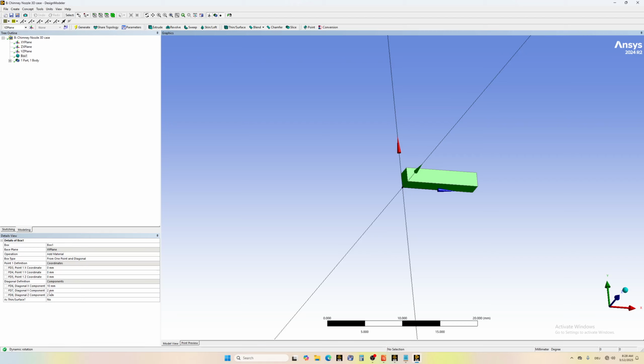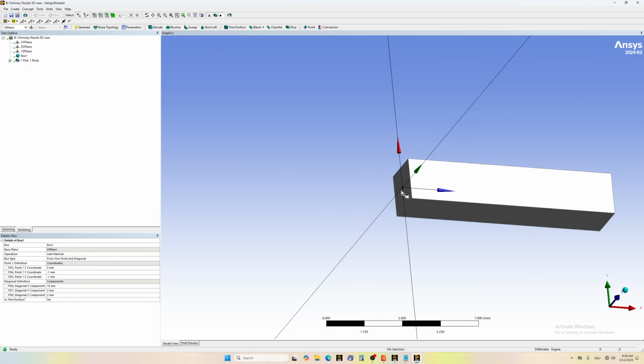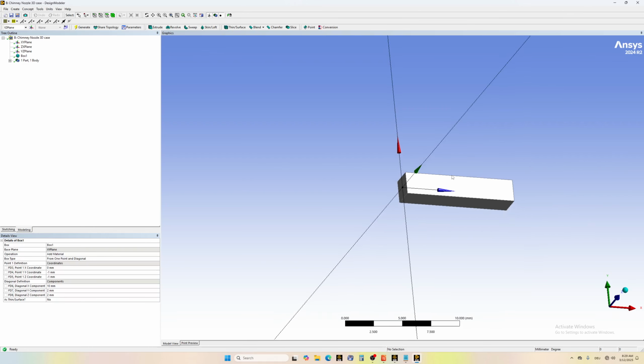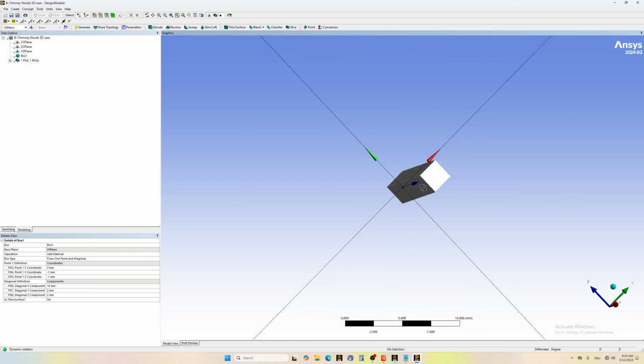So we will put it exactly in the middle, and for that all we have to do is just translate the box by -1 and -1. Again generate, and you see now it's exactly in the middle. Use scroll to zoom in and zoom out if you don't know this. Okay, so let's go back, let's create the plane.